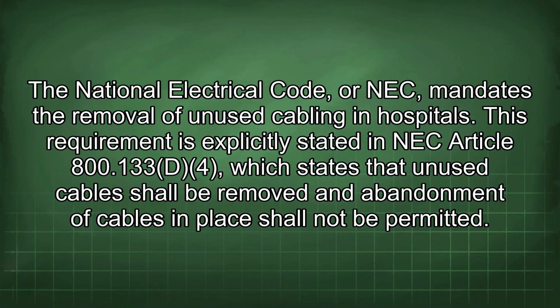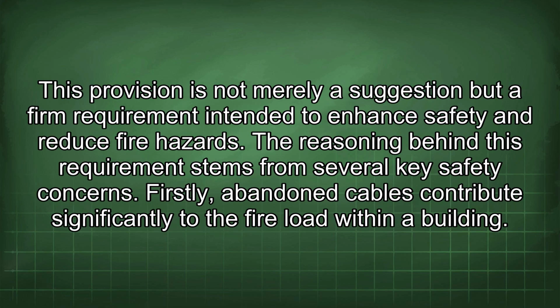The National Electrical Code, or NEC, mandates the removal of unused cabling in hospitals. This requirement is explicitly stated in NEC Article 800.133(D)(4), which states that unused cables shall be removed and abandonment of cables in place shall not be permitted. This provision is not merely a suggestion, but a firm requirement intended to enhance safety and reduce fire hazards.